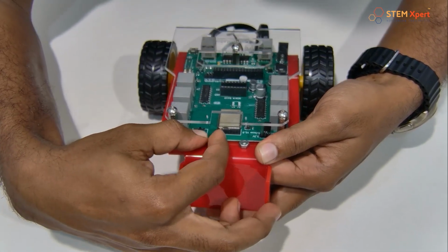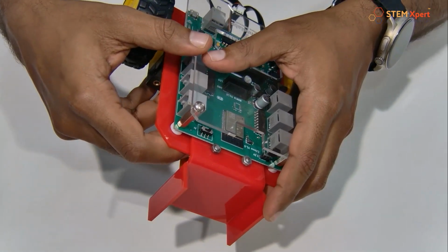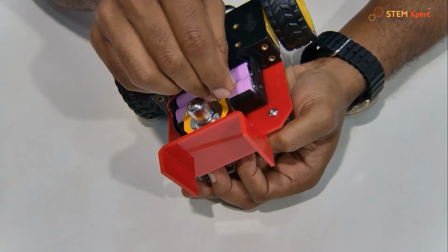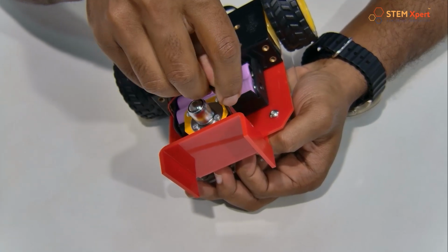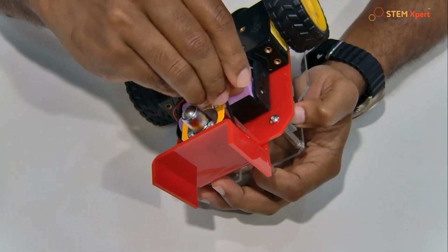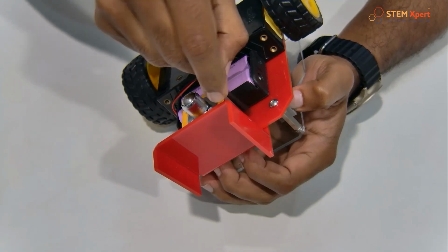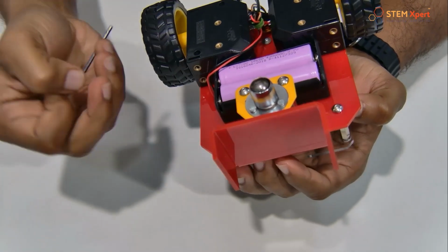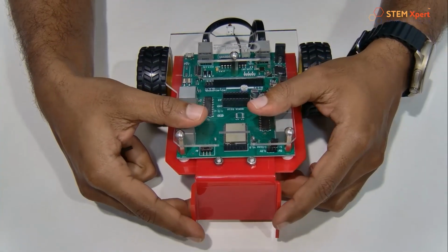and rotate. Once it is like this, you can turn it around and there you might need to use this Allen key. You can tighten the screws by using the Allen key like this. You can put a finger in here and then use the Allen key to tighten the screws. The same way is the second one. Rotate the screws in clockwise direction. Then this is how it looks. Now it is fixed.